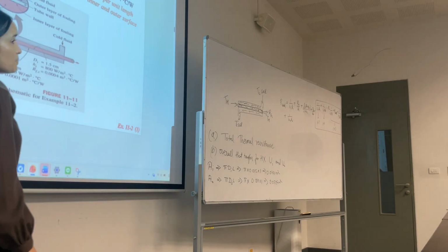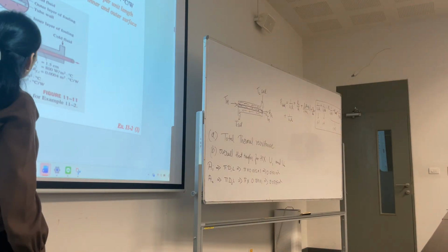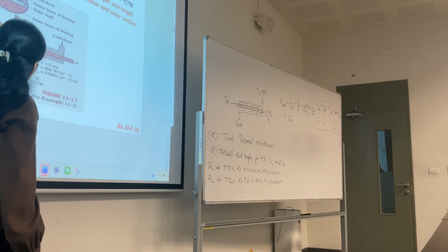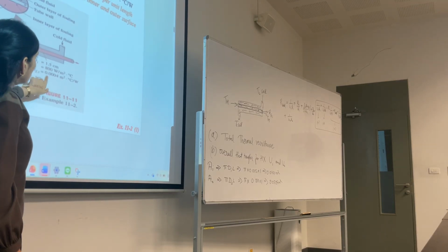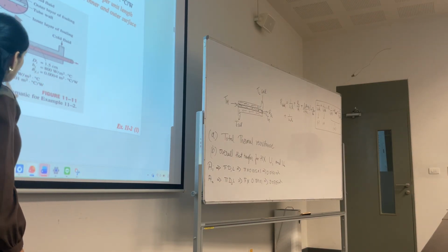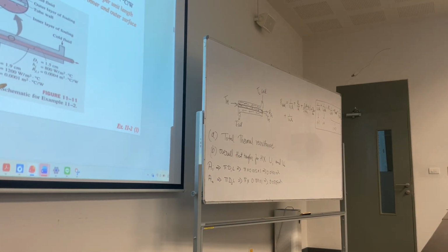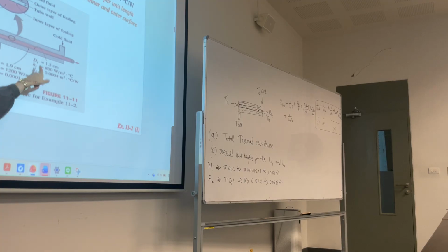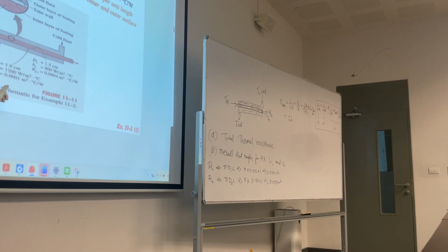Okay, these pipes are very old. They have some corrosion, or some precipitate deposited inside the tube as well as outside the tube. So those are called fouling factor resistances. RFI is for the inside, RFO is for the outside. So you have to add these when you are calculating total thermal resistance. When you are calculating inside you add this, when you are calculating outside you add this.